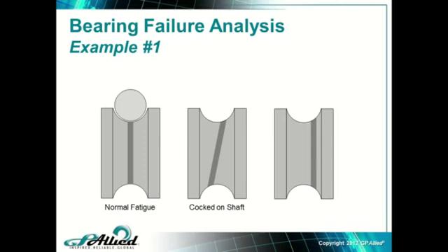Well, they figured, well, both bearings came with expansion rings. I guess we'll put them both in. And they put them on the outside of both bearings, and what happened is as the shaft got hot and expanded, and all shafts do, as the shaft expanded, it bowed in between the expansion rings, which caused axial loading of the roller up on the edge instead of in the center where it's supposed to be.